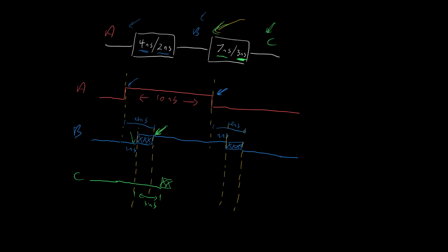So from this point here, we have to wait 7 nanoseconds. This brings us to halfway between there and there. So this, if I'm not mistaken, is going to be 7 nanoseconds, corresponding to the propagation delay of the second logic circuit. And when we reach the 7 nanosecond mark, after the input has become valid, then the output is going to be valid and remains valid up until at least the next event at the input, like this.